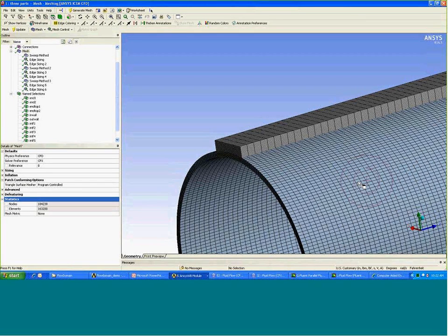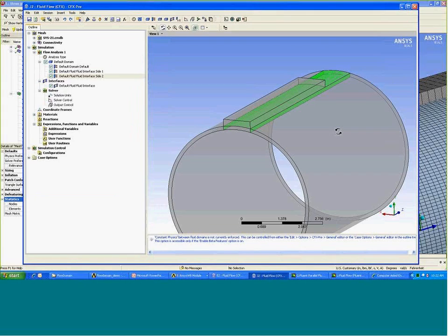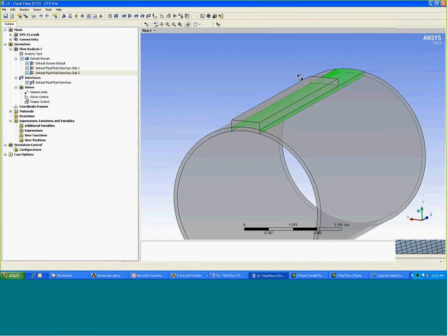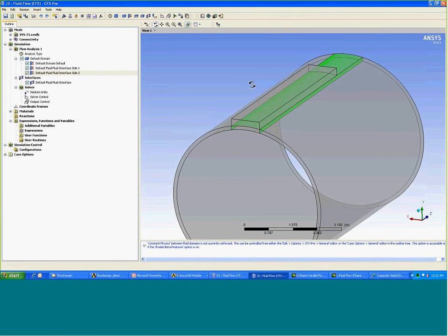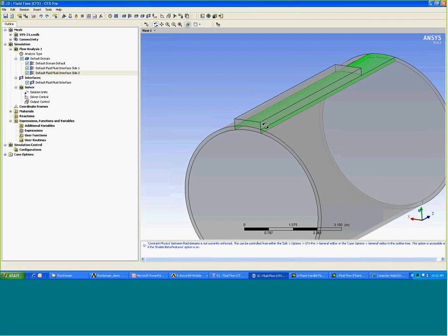What would CFX and Fluent do with this mesh? First, look at CFX. When we bring the 3 parts into CFX, CFX can identify the interface by default. Without doing anything, because the elements are not matched exactly on the 3 surfaces, CFX generates a default fluid interface.